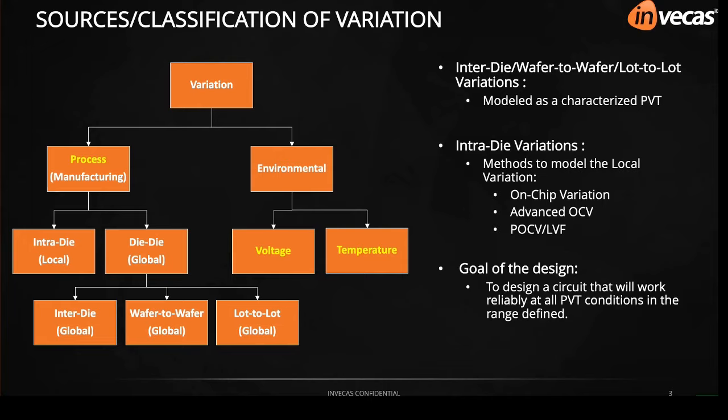After a lot of study, it came out that there are some unexpected changes happening in the manufacturing process which are causing the change in the transistor behavior, which in turn results in the failure of the chips. These changes are referred to as variations. At the advanced technologies, variations are becoming a very common or predominant cause for the failure of the chips if they are not taken care of properly in the design closure. Here, when we are talking about variations, many of them are unseen and unpredictable by the engineers who are really working on the chips and doing the sign off.